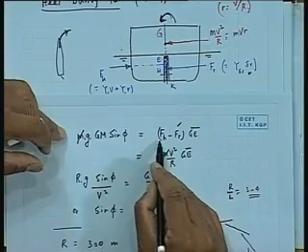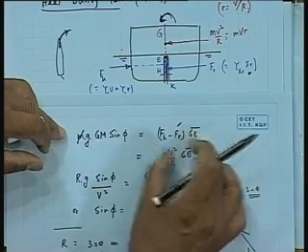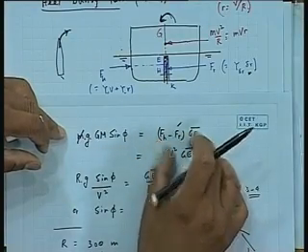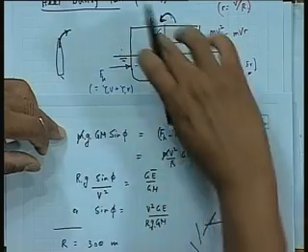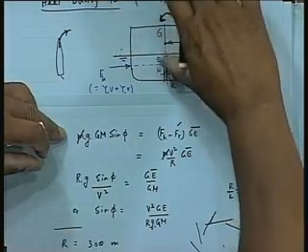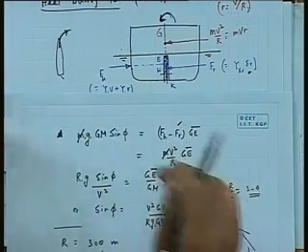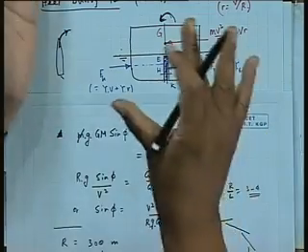What happened? Earlier it was Fh minus Fr G, now it is Fh G. Which one is more? This is much more. So suddenly it is going to find much more turning moment. That is why if you suddenly stop, it will have a jolt and try to heel more. It may in fact heel more and may capsize. This is why it is suggested that you should not bring the rudder back to 0 when it is making a sharp turn. During the turn you should do it very slowly so that there is an adjustment time.